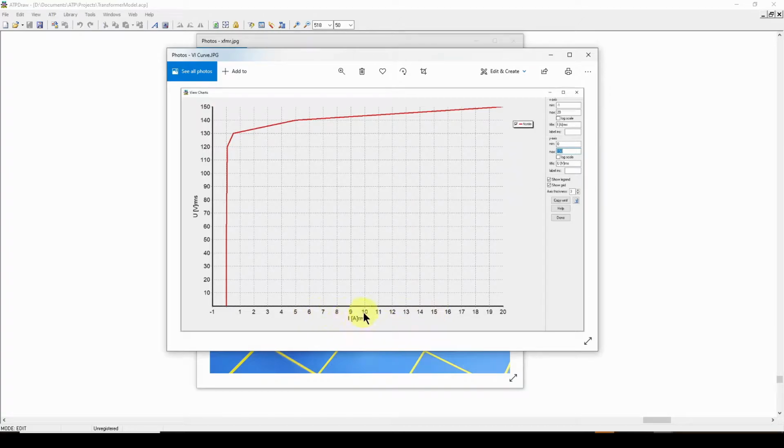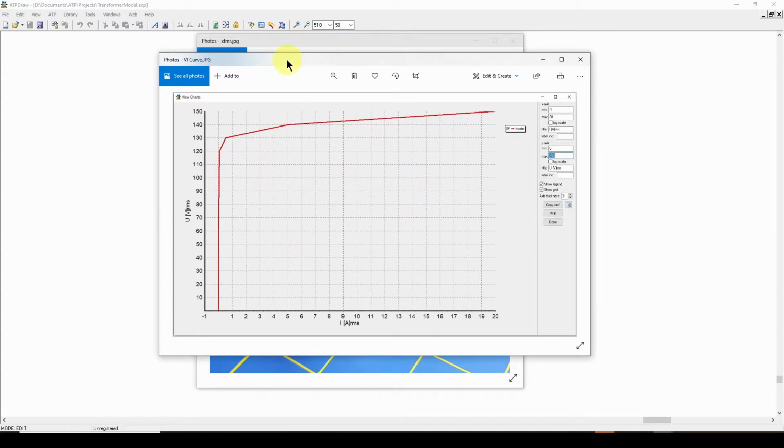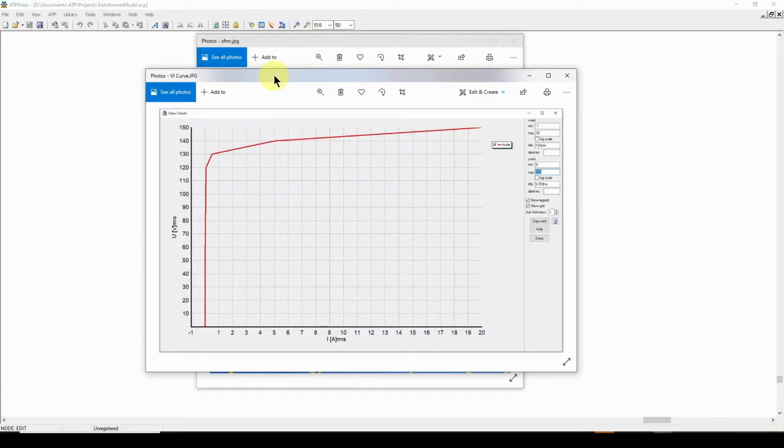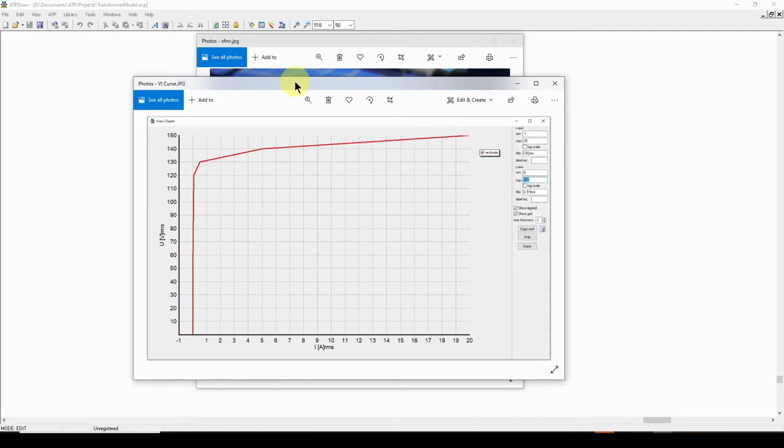It's just a characteristic of the iron core transformer and the 120 volt or 117 volt winding inductance. So we put that into the simulation and generated some results and checked them versus our bench test for energizing this transformer and looking at the transient that we get.